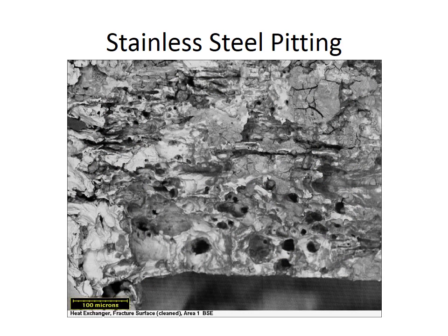In low-temperature thermal desalination plants, the stainless steel alloys that make up the evaporation plant's tanks are exposed to high chlorine ion concentration due to salt water, which can interfere with the stainless steel's ability to form a fully protective film. Tiny local fluctuations will degrade the oxide film in a few critical points called pits, where corrosion usually takes place in stainless steel. Corrosion will be greatly amplified at these pits, and in extreme cases, the sharp tips of